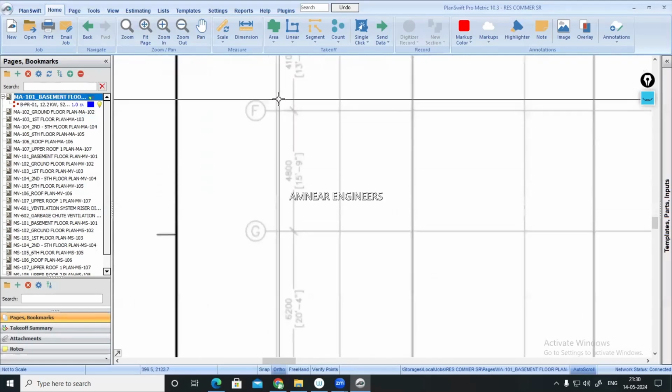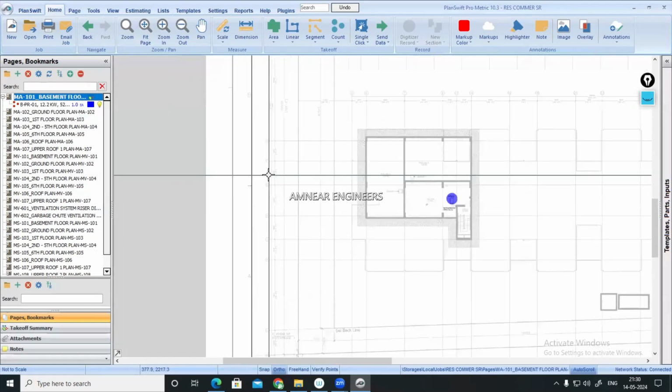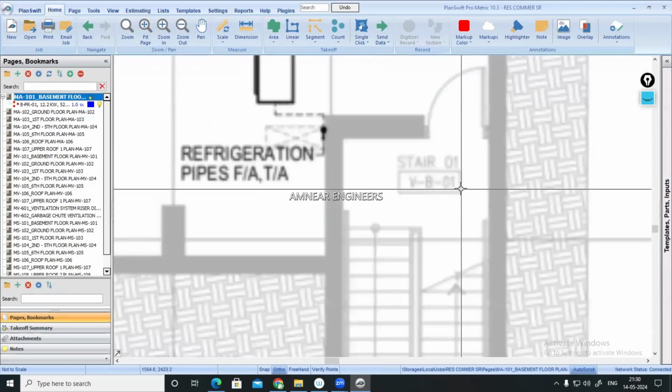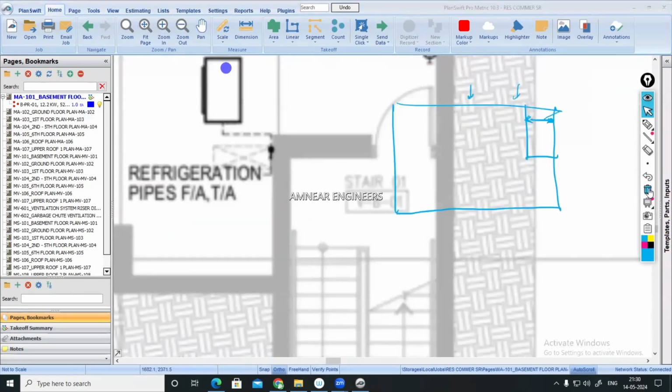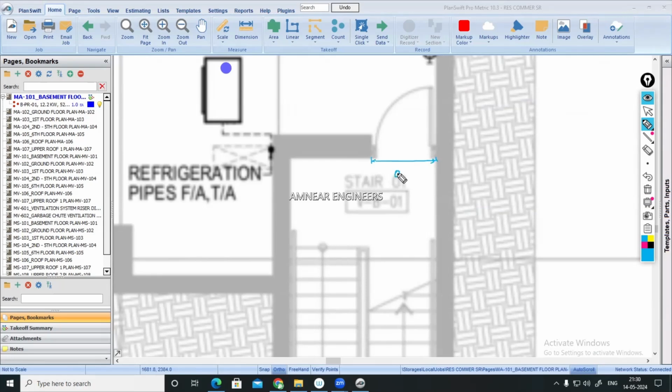Anyhow, I'm having a lot of dimensions there, so I can scale it. Even if you are not having any drawing with a dimension, no problem. Any single door width, including the frame, this width you can consider 0.9 meter or 900 mm. That is standard only. Or for the internal dimension, you can take like 800 millimeter or 0.8 meter based on that. But it is rare; if you're having any known distance, you have to follow it accordingly. Then only the accuracy will be there.